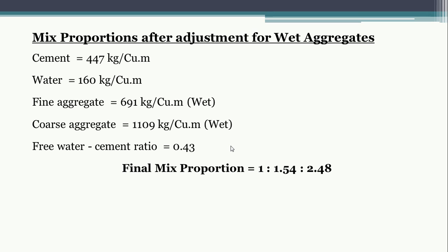Also there we used fly ash, and the method of placing was pumping. But here those things are not there, so even for the same mix proportion, since we are not using chemical admixture, the workability range is less, between 50 to 75 mm.